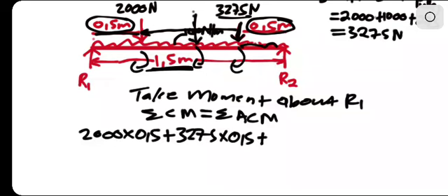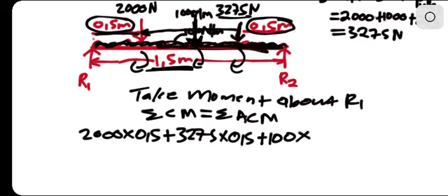Consider this, we have a distribution. The distribution also will act clockwise, guys. It will point downwards. I will take it as 100 Newton per meter there. Maybe I will show you that force, which is acting there in the middle. Remember, it's in Newton per meter. We'll say 100 Newton per meter multiplied by the whole beam, multiplied by 1.5.